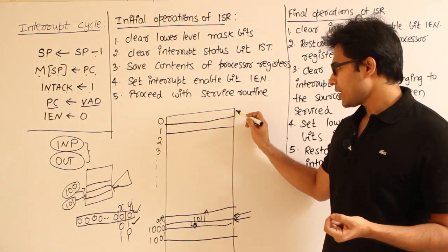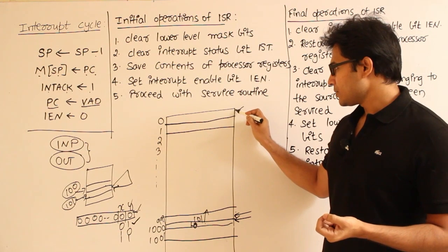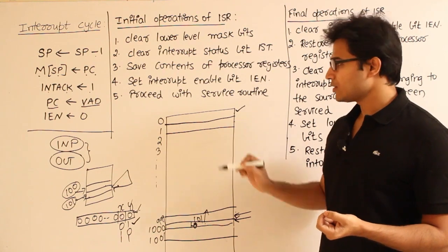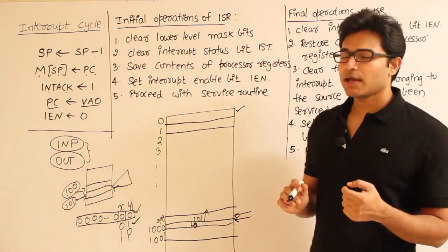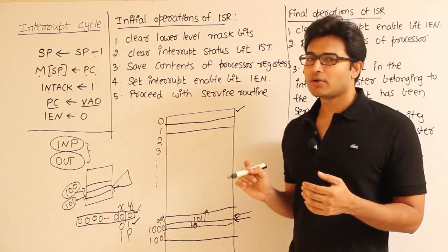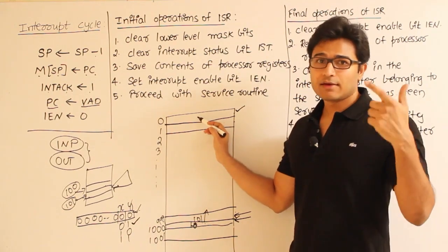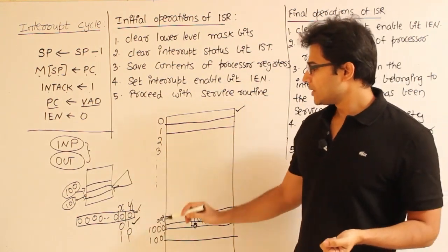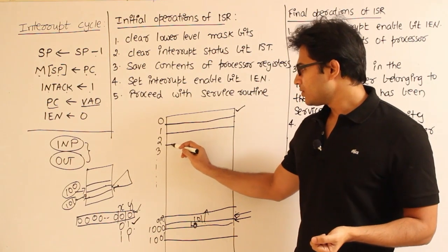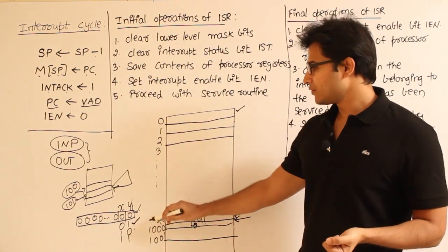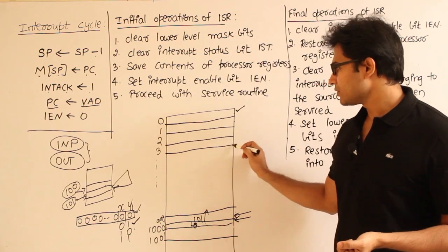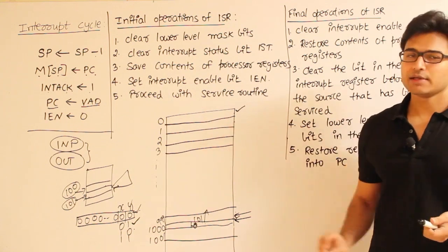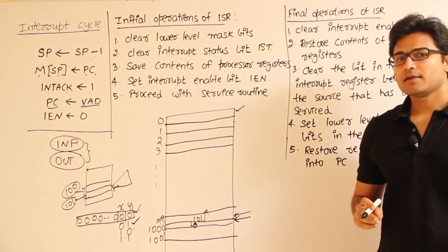So if the ISR, the interrupt service routine of the hard disk, is going to start here, it is impossible to start the next program here, the ISR of the printer. Therefore we are not actually going to put the ISRs at this location. What we will put here is the address at which that ISR is present, right? Similarly, if it is the reader, we will be going here, 10. If it is the keyboard, we will be going here, which means 11. Got it? So at some fixed location, we are going to place the address of the interrupt service routine.